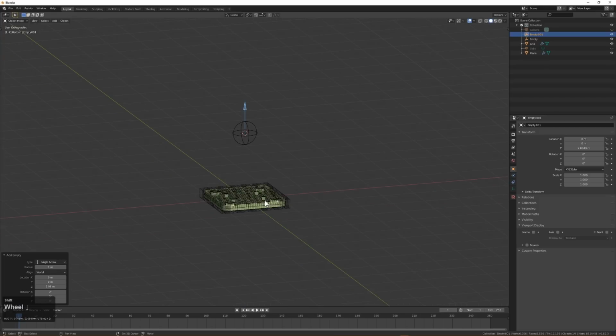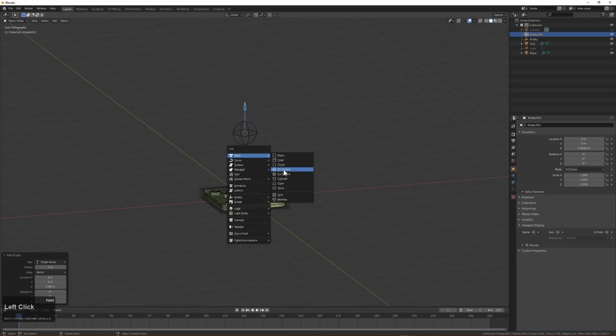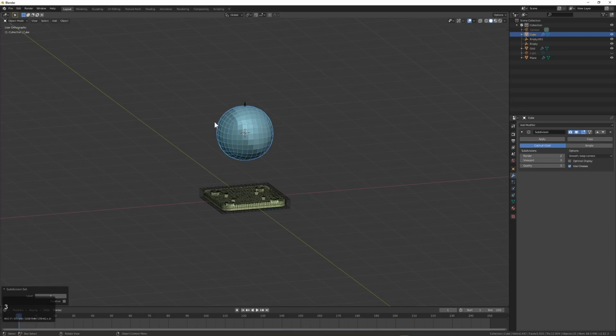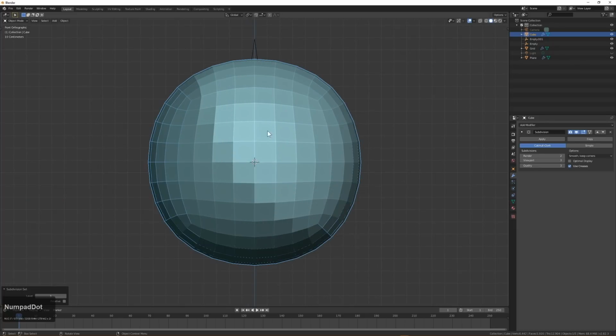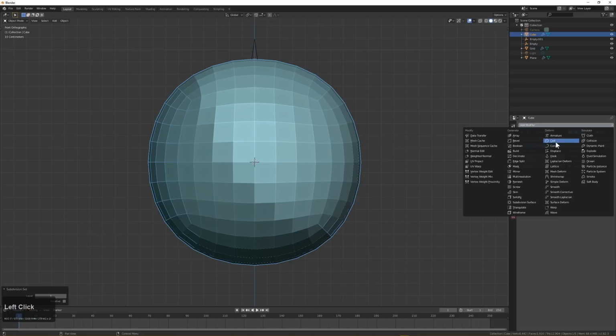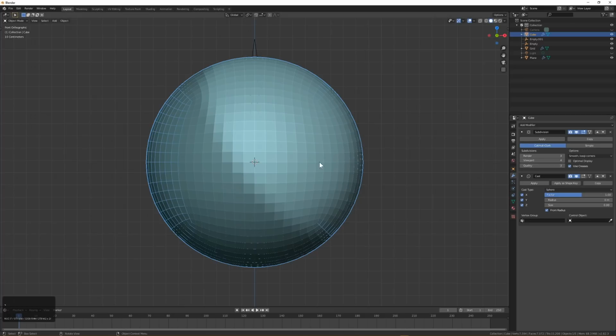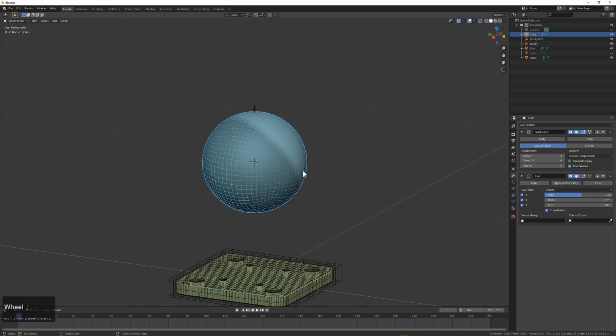All right, continuing on. So at this point, what we want to do is bring in a sphere. So the UV sphere isn't my favorite sphere, so I'll just go ahead and introduce you to the concept of making a correct sphere. So with this cube, we'll press Control 3, which will put a subdivision modifier on it. But if we press 1 and numpad period to focus on front view and zoom in on this, it doesn't really look very spherical. So by adding a cast modifier and setting the factor to 1, we can actually add additional volume to this and get this to look just like a sphere, and a little bit more subdivision. And we can actually even right click this and shade smooth, and it looks pretty good.